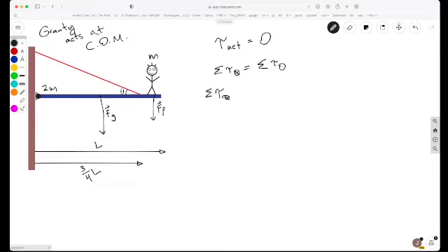Finally, we have the tension from the rope. This rope's attached to the wall, it's holding this plank up, and ropes can only pull along their direction. So this should be a straight line. It came out curvy. But this we'll call tension. I put it as T, but this is just a force. This is something we'll do a lot. It just helps when we're solving equations to not have so many F's floating around, but this tension is just the force that the rope applies to the plank. So what I've drawn here is called an extended force diagram. Let me write that here.